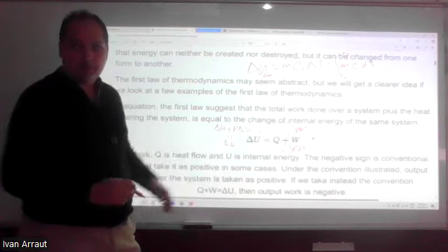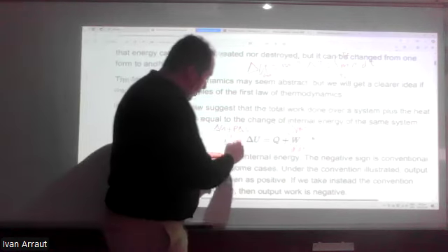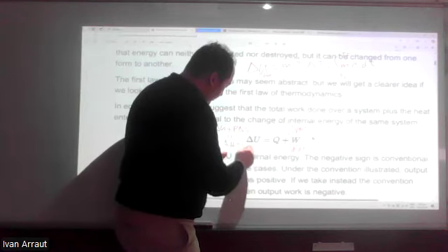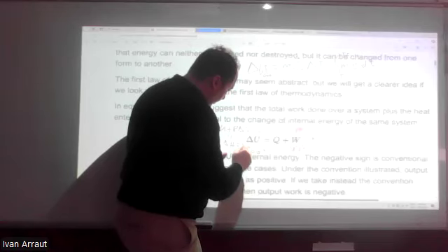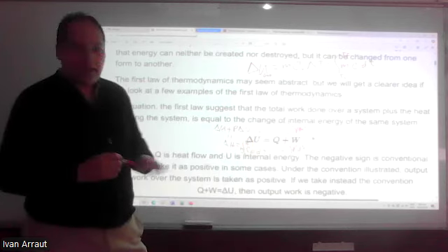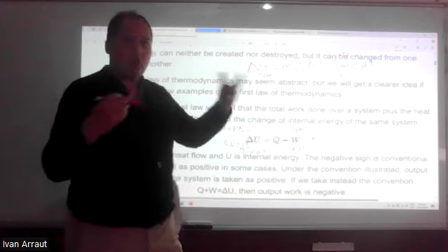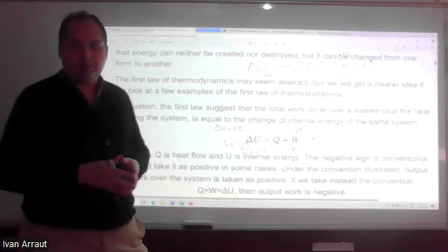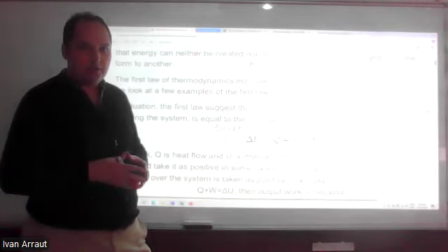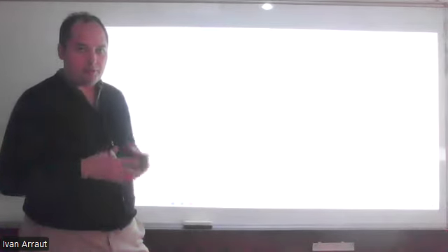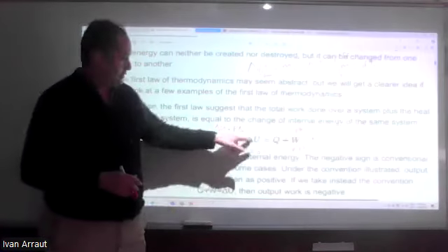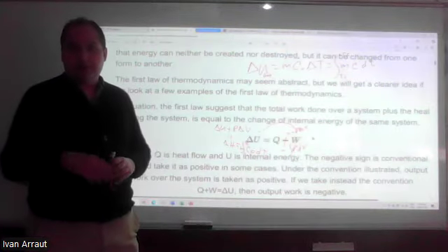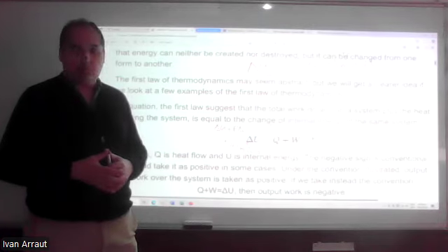Enthalpy is another thermodynamic property, and it is the integral of the heat capacity at constant pressure, dT, multiplied by the mass, from initial to final temperature. In the thermodynamic tables, when they evaluate some properties or processes, they use enthalpy instead of internal energy, because sometimes it's easier to do it that way.